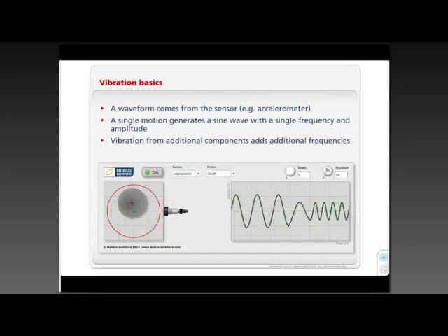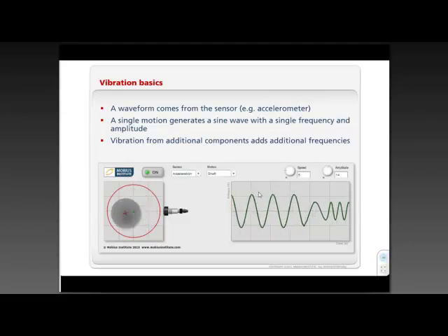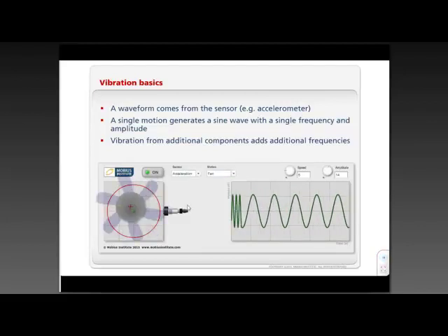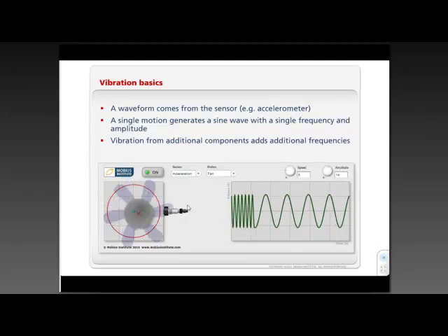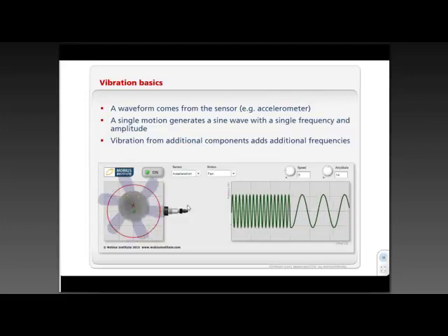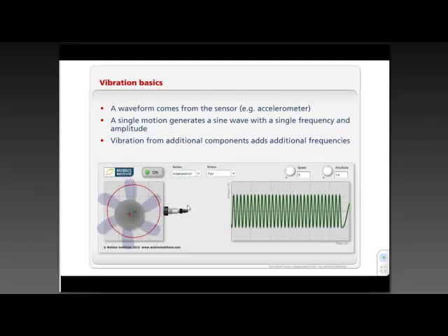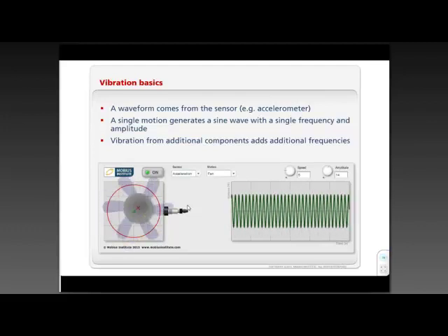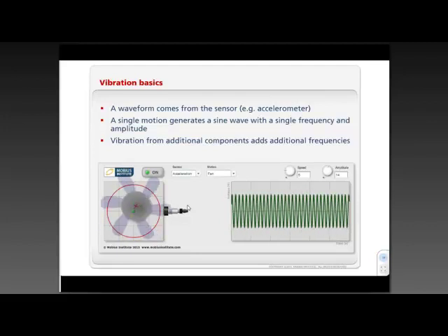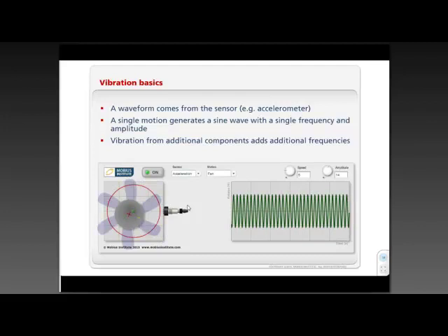Now again, this is just one source of vibration, and if we had a fan on it, I mean, this looks a bit odd I suppose, but we now are just picking up the motion that you might see if there was a problem with the fan blades themselves. It is a higher frequency because in this case we have 6 blades, and that's a sort of a simplification, I guess, of how it would move if, as each blade went by, there was 6 times per revolution, we end up with a higher frequency.